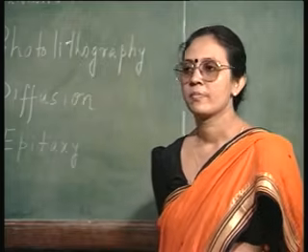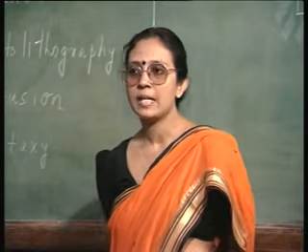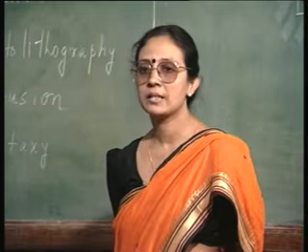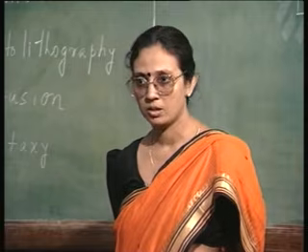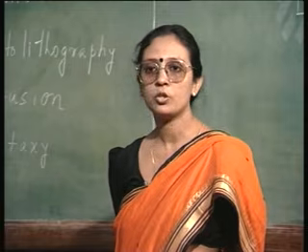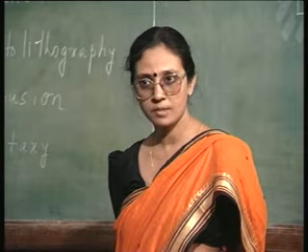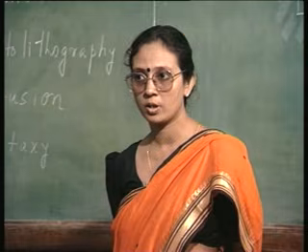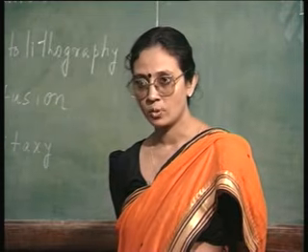Now, think for a moment. This N epitaxial layer is going to be the collector of the bipolar junction transistor. Obviously, I am not going to have just one transistor in this entire silicon chip. I am going to have thousands of transistors when I am talking about LSI or VLSI. What does that mean?